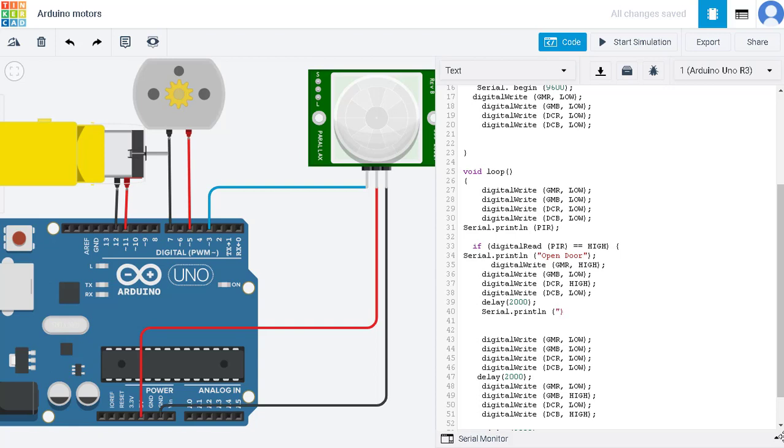So I am going to do something in here. I'm going to print a message, and the message is going to be wait. It means that the door is open, so it's waiting to close. And before each message, I am going to give a delay of less than 1 minute. So remember, here the number that we type is in milliseconds. So when I type 200 milliseconds, it is just a fraction of a second. Well, let's say better 500 seconds in order to complete this message. But of course,